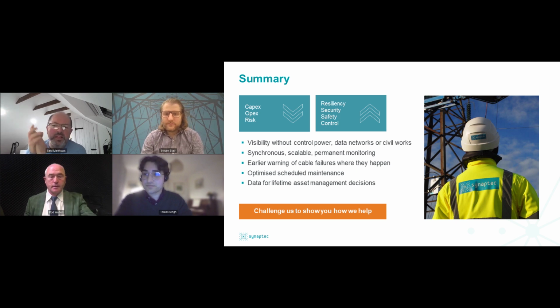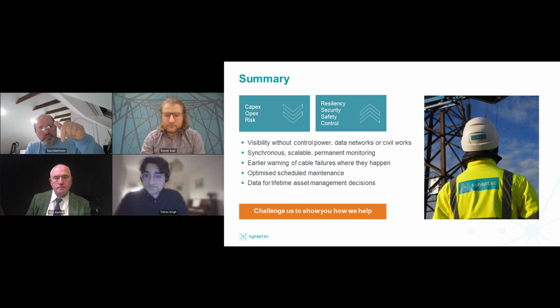I suppose from an economic perspective or a cost perspective, this is probably the best way to deal with that complexity, because any other manual or inspection regime or automated distributed sensing process like partial discharge monitoring, you're going to have to go and put sensors and servers and data networks and power supplies at every point. It doesn't scale very well, but fortunately, the way the architecture of our system is designed is that you have one box centrally looking out at many locations.